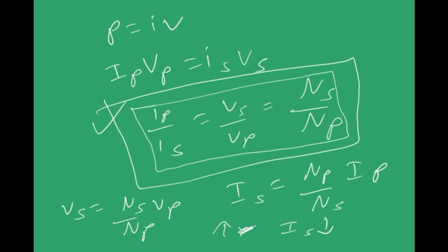But however, in practical situations, we have energy losses, right? And they can be due to flux leakage or resistance of windings. Here we assume the primary resistance and current are small. Of course, we also want the secondary current to be small. I mean, the secondary voltage, we take it like this, right? This is Vs. This should be actually open circuit. Then our formula works perfectly. Or if you want to approximate it, it should at least be connected to a very, very large resistance. This is one more assumption we made. And other effects can be because of eddy currents and hysteresis, there can be some energy losses.